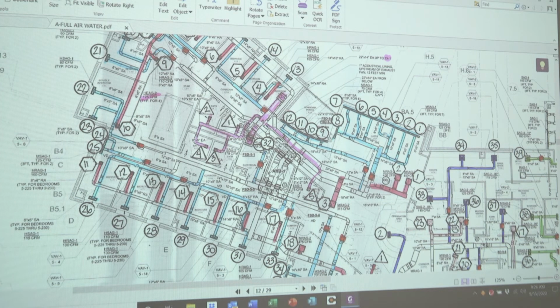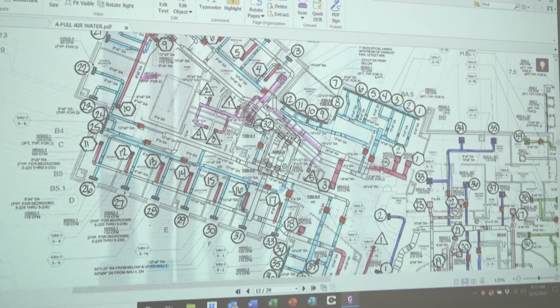You have common area VAVs that are providing ventilation and air control over the curtain wall systems. Again, that's one large box servicing that whole exposure. Another box is handling that exposure. So there's a large overlap in zone. There's a lot of infinite control because you have a lot of different means to control spaces.